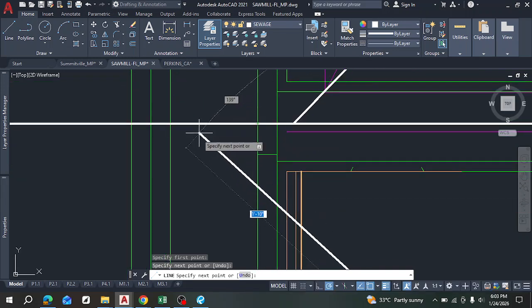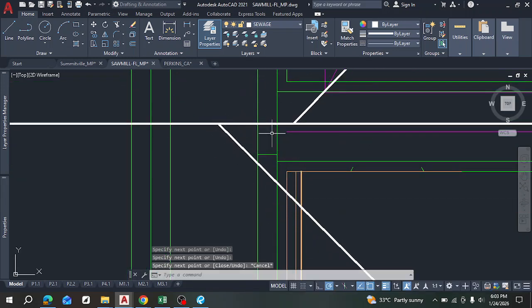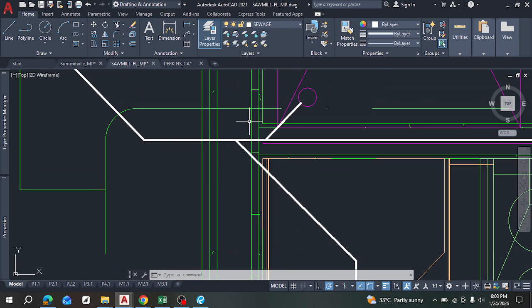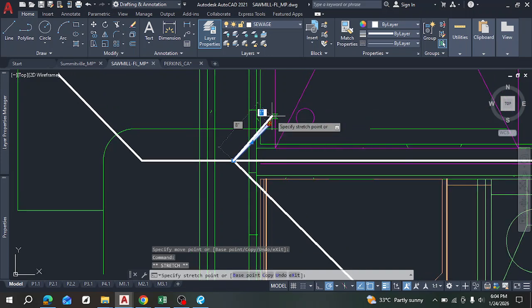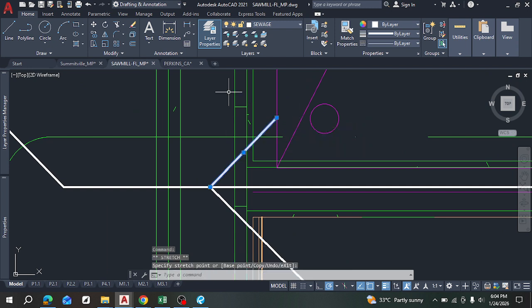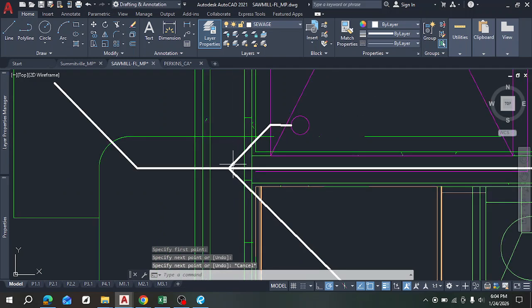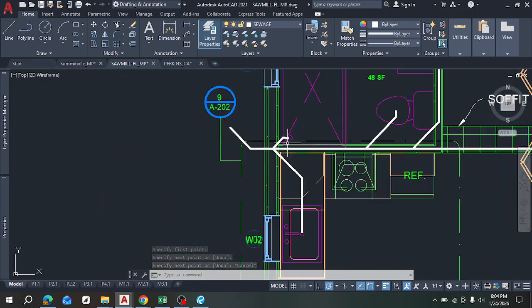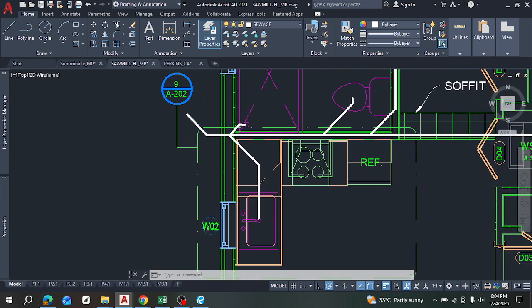Now I want these two to meet at this point because if there are two of them, it's going to be in two different fittings. So I want to help the guy by just putting one fit. I mean, the person on site physically would choose which one works best for him, right? He can decide to separate them, or he can decide to do them together, right? So this is from here. So I want them to meet here so I can just vent two of them at once. And thankfully, things like bathtub and sink, they don't usually have very high requirements when it comes to venting.